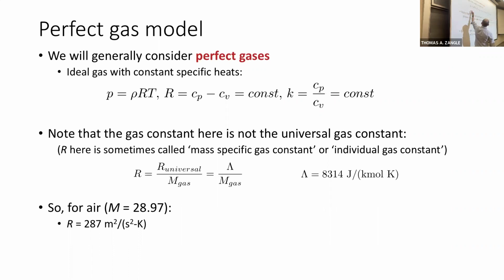So we use this form here because it's more convenient when we're dealing with fluids, right? Because this relates now all of the things that we have conservation laws for. So we have pressure, which we're used to dealing with from momentum conservation, right? Density, which is the thing that we know is going to vary within a compressible flow.